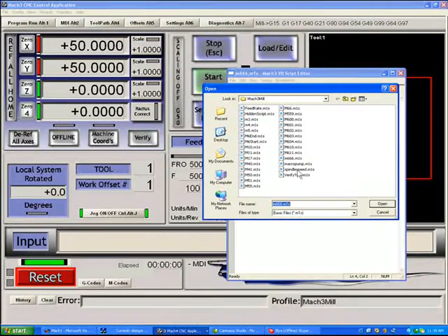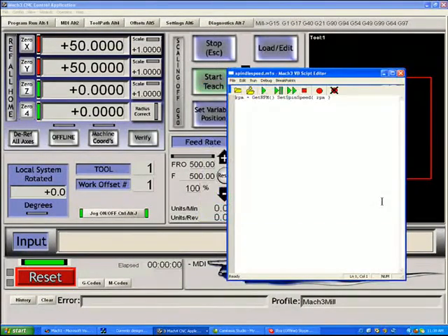For example, here under spindlespeed.m1s, this is a script which is called whenever you set a spindle speed. So when you type S200 in your MDI line or in a G-code program, we will use the command RPM equals GetRPM, which puts the value of that S command, or the numeric portion of it, into a variable called RPM. We then set the spindle speed to that RPM.